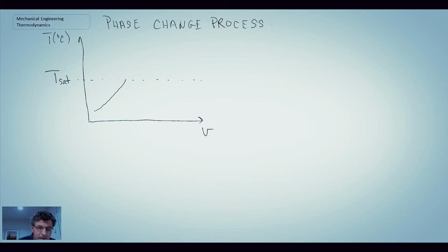So this is a line that's at a constant pressure is what I've drawn here coming up to the saturation temperature. So what happens is we increase temperature, then we get to a point where we hit the saturation point, and that's when we're going through the phase change of boiling, and we refer to that as being a saturated mixture.